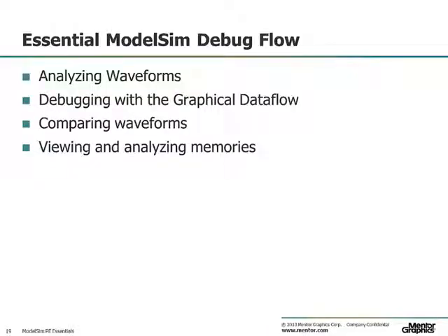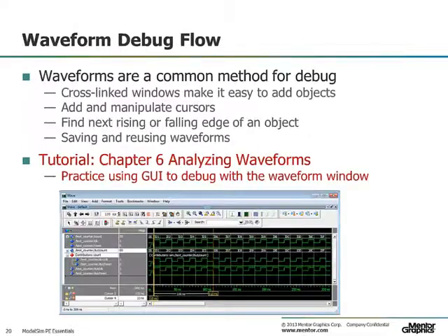We're going to highlight the most common debug tasks so you can get started deploying your next project with ModelSim. The first one, and probably the most common, is the waveform debug flow. ModelSim MDI interface allows cross-linking of windows so that it makes it easy to add objects from one window to any other. You can have context sensitive, so if you're looking at a particular part of your design hierarchy, all the other windows are relevant to that particular design hierarchy.